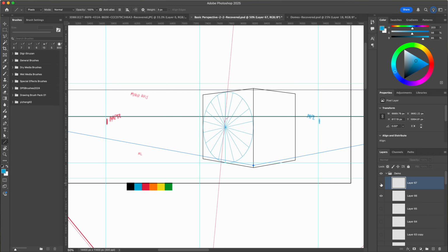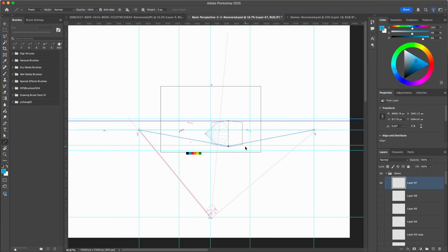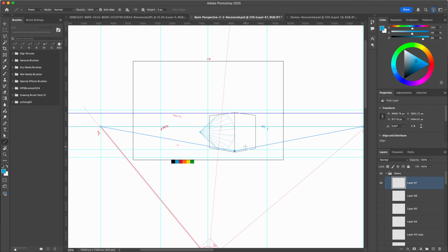So those accurate radials in perspective, and then using a projection point from our minor axes along there, we can create a convergence point and have those radials meet it, which creates a cone in perspective with accurate even segments along here. So these are all even segments. So it's kind of like 3D modeling the old-fashioned way, right? So that is our basic ellipse demonstration.